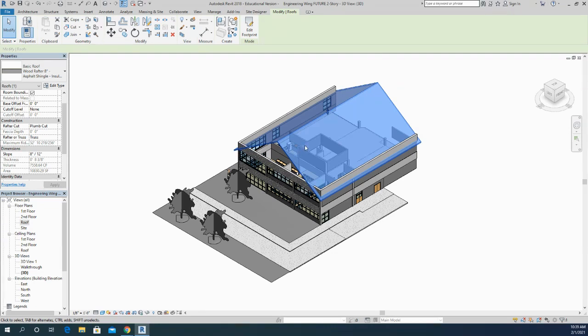It also gives you area, which is actually probably more useful for a roof. If you're looking at areas, so you know how much material to purchase, that's how we find that information. So hopefully that helps with creating a sloped roof and using the Trim/Extend to Corner tool and creating floors and extending them into the core of those floors.